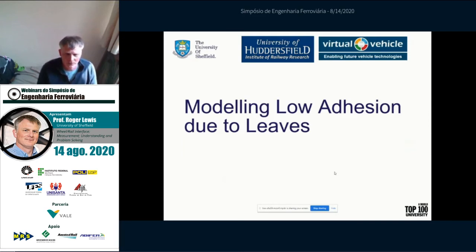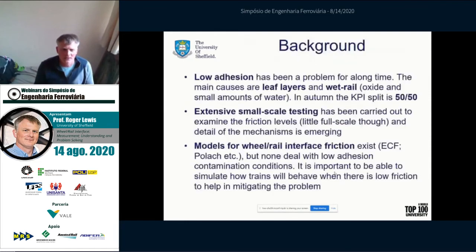And in fact, we've just finished a project with FRA where we built a similar model to look at top of rail friction modifier performance, both in terms of its friction effects, but also in terms of consumption from wayside applicators. So the idea behind this work is that we do some tests on either a small scale or a full scale rig to produce some creep curves, and then we use those to parameterize a model. Here we followed the kind of POLAC modeling approach, as you'll see when I go through.